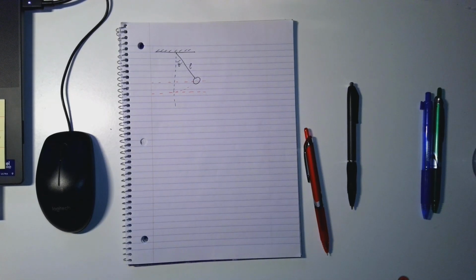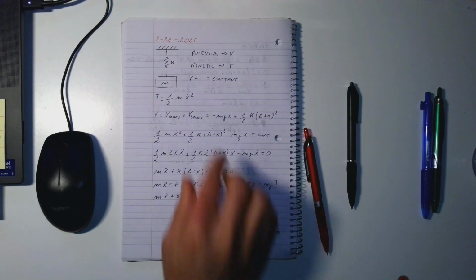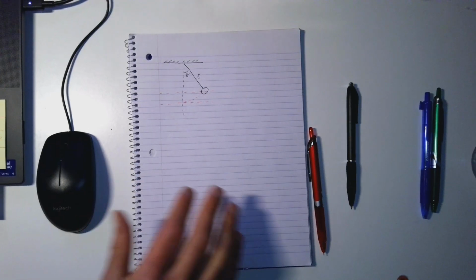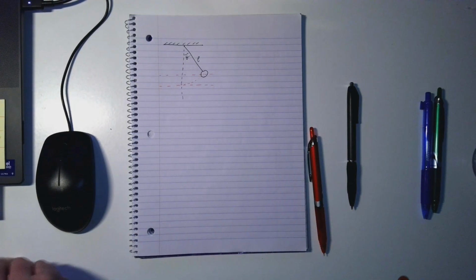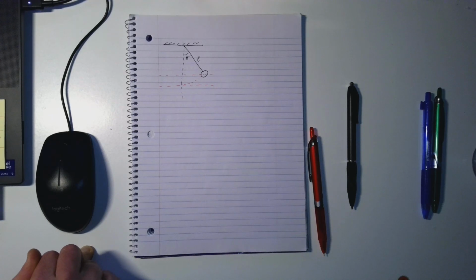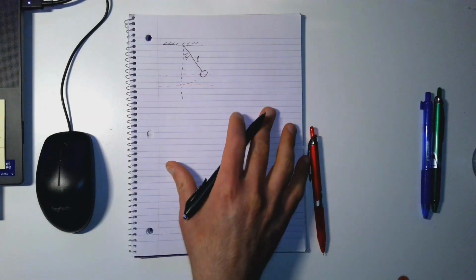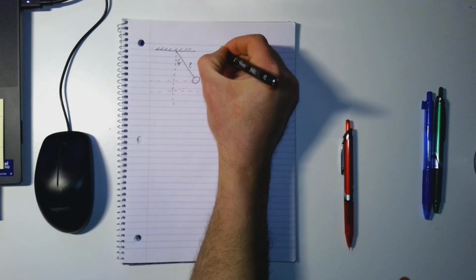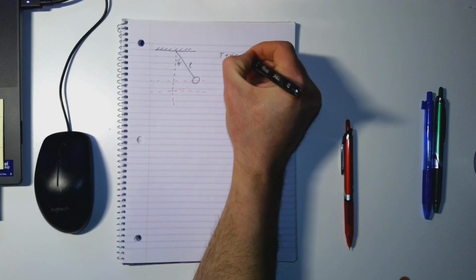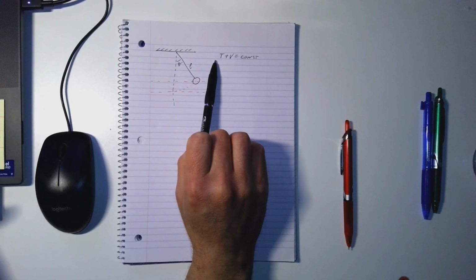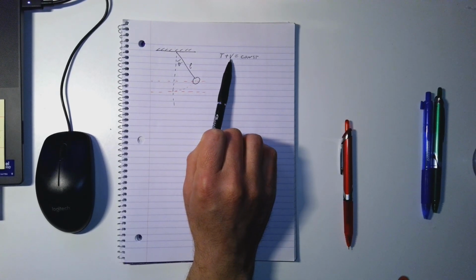So in the previous example we used the translational kinetic energy, which we defined as 1 over 2 m x dot squared. But in this case, since we are looking at rotational motion, we can use the rotational kinetic energy. Make sense? So, exactly like we started before, we start from the principle of conservation of energy, so we have T plus V equal to constant, and even in this case we have to find the kinetic energy T and potential energy V.